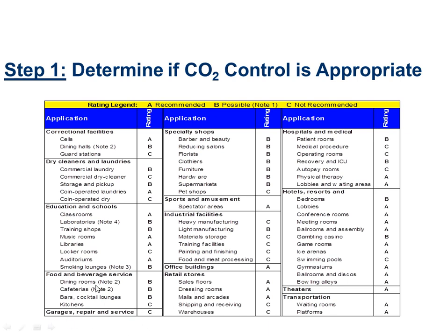Anything to do with vehicles, like parking garages or car dealerships, can't be done with CO2 sensors. However, we do use CO sensors, carbon monoxide, to monitor those spaces and control the ventilation air. Pet shops are a bad idea because animals smell no matter what, so you want to cut back the ventilation air on those spaces. Depending on what you're doing in a manufacturing facility, it might be a usable idea, it might not. Warehouses are a bad idea because you don't have a lot of people working in a given volume of air. Most medical spaces we stay away from, leave the operating rooms and stuff like that alone.